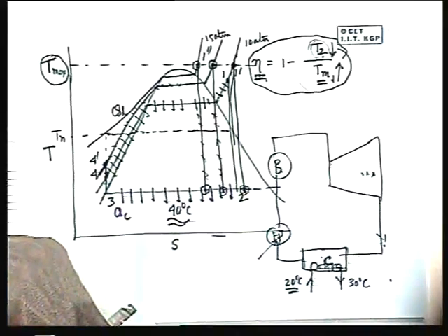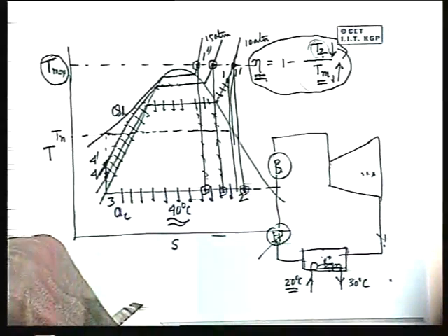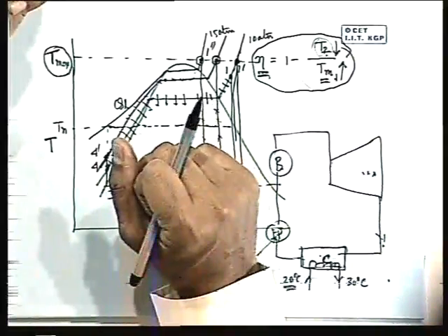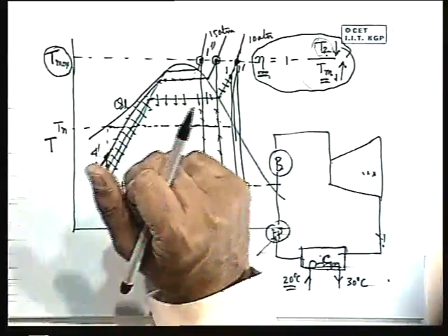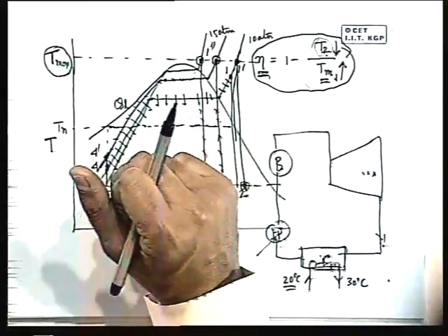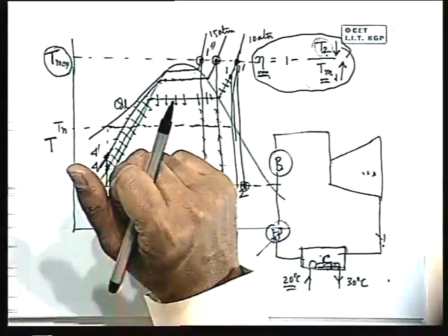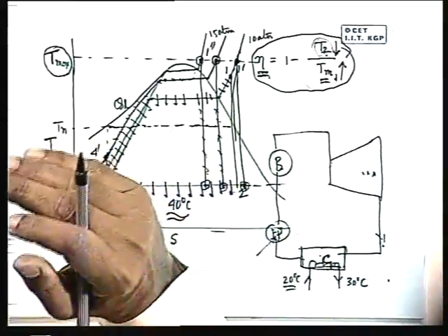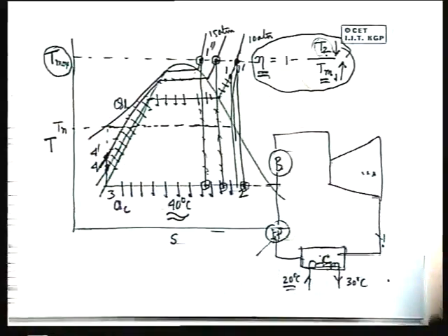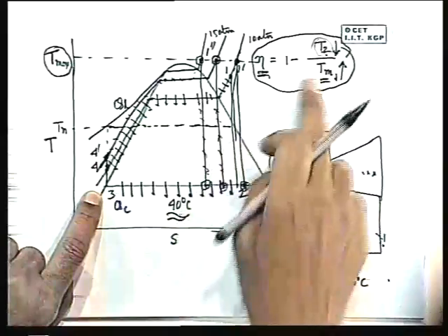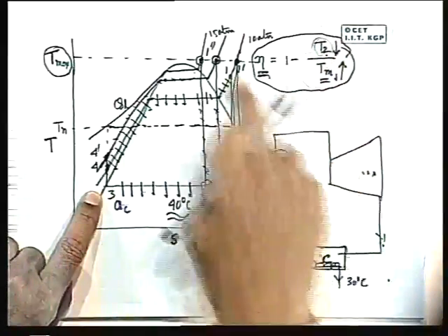Then you pump the circulating water, steam is not condensed at all. You understand? Because the steam temperature is lower than the cooling water temperature. Steam may get heated, it may be dried up also. So therefore the saturation temperature corresponding to the pressure at which the steam is condensed must be higher than the available cooling water temperature. Very important. So that sets the limit of the pressure, and accordingly the temperature of the practical cycle.